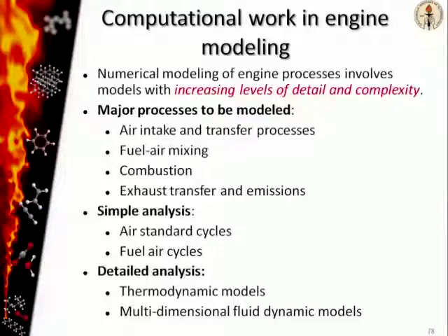There are numerical models of increasing complexity and levels of detail to simulate engine cycles. The major processes you're trying to model in these simulations are the air intake and transfer process, the mixing of fuel and air, the combustion process itself, and finally the exhaust transfer and emission process.